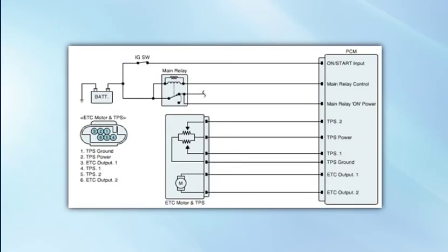Typically, once a fault has been identified, the diagnostic routine in the service manual will instruct you to perform checks of the circuit. Whether or not you have a code, you should know how to diagnose a sensor circuit. Depending on the type of sensor, you might check voltage in the harness or resistance of the component. Let's start with resistance. Measuring resistance is the process of measuring the resistance to the flow of electrons through the circuit.